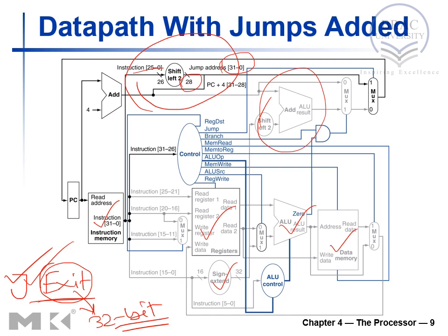Sorry, not this one. We perform the concatenation operation, and just by concatenation operation we get, see here it is written program counter 31 to 28, the bit value of the program counter. So we just concatenate it and it goes to this multiplexer. So this multiplexer outputs this value. This is the value that is jump address 31 to 0. Okay, so this is how jump address gets calculated.